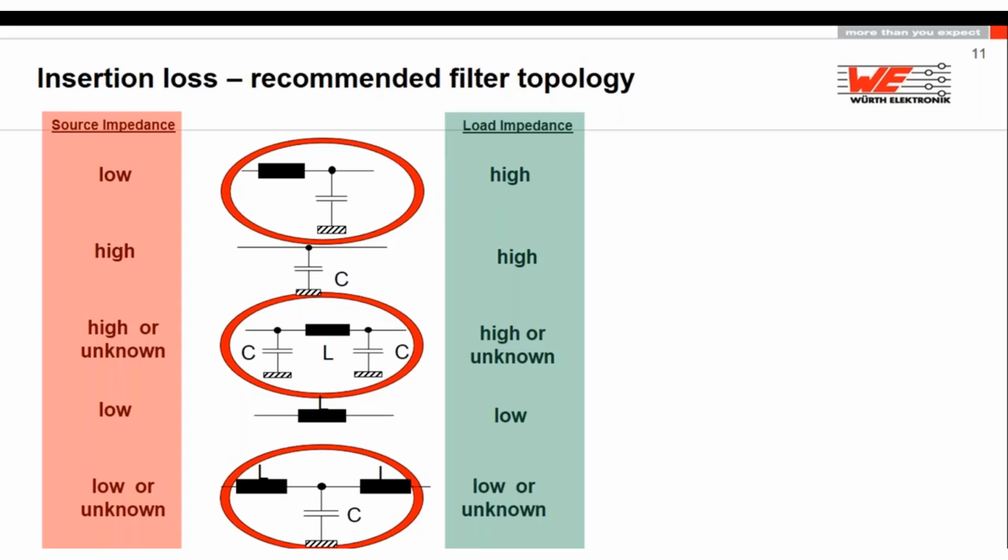With the Pi filter, I play with the capacitors. And when I see the capacitor doesn't have a really big impact, I go back to my LC and try to play with two different inductors. So I have my T filter. One of those filters will have a massive insertion loss, and you will find the right solution just by trying, if you don't know exactly the system impedances, which is mostly the problem. It's not like in a university where everything is 50 ohm. In real life, you will find that the system impedance is very, very rarely 50 ohm.